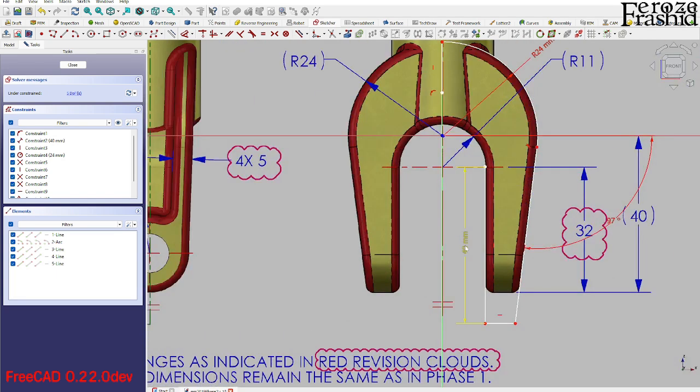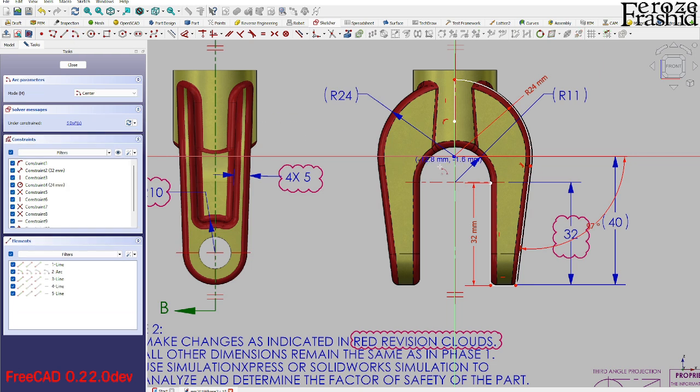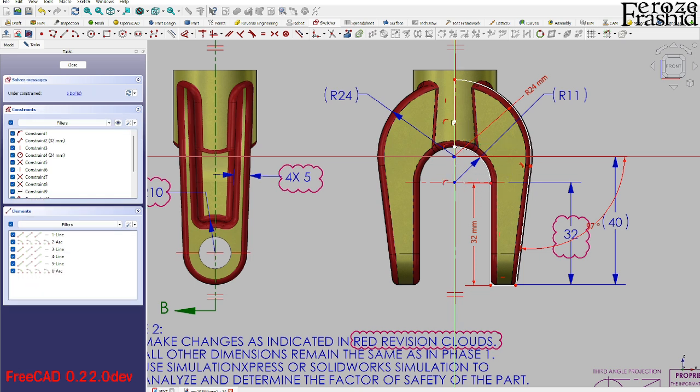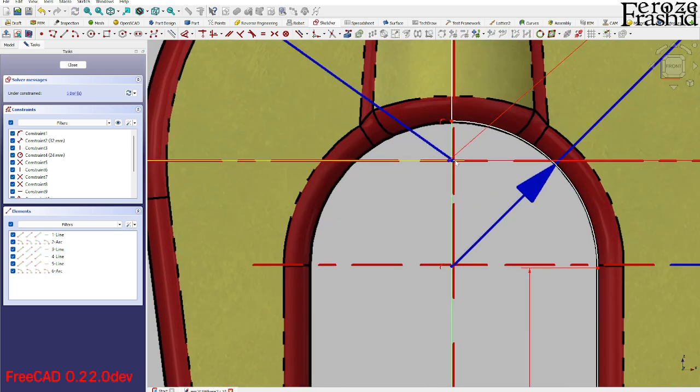And then this 40 obviously will be changed to 32, right? So here, and now I can create an arc from this point. So this is going to be, and then I can come make these two points coincident, and that kind of took the coincidence away from here. So let's put them back,